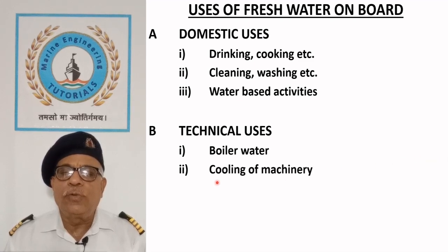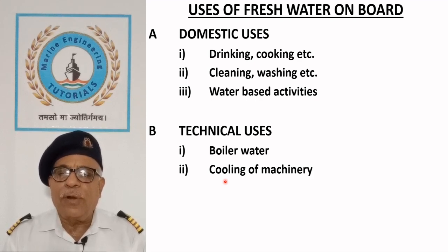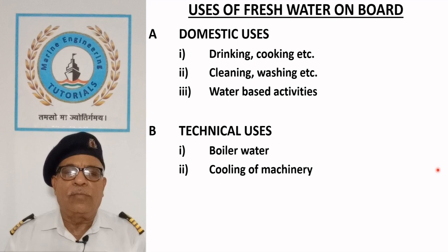Freshwater is used as jacket cooling water to remove the heat from diesel engine and compressor cylinders. In addition, use of low temperature or central freshwater cooling system makes the seawater system short and helps in reduction of corrosion due to seawater.